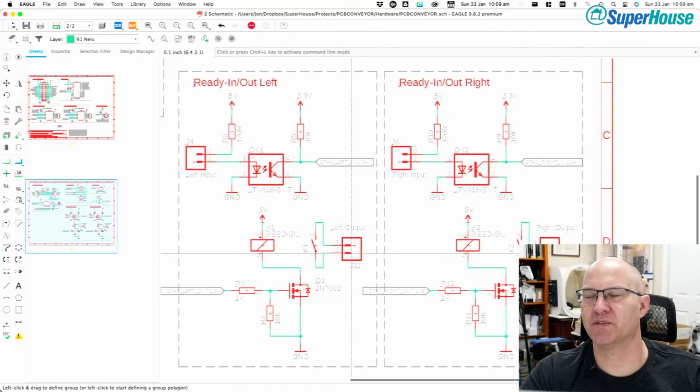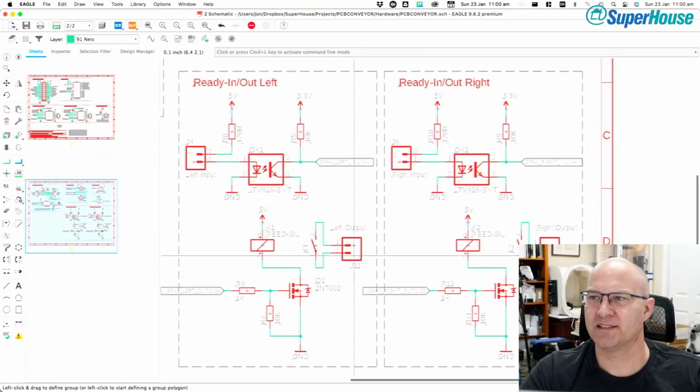The PLC or whatever it is in the next machine can simply put, say, 24 volts onto this, and then it'll take an input with a pull down on the other side or whatever it does. So with this, we can just switch this relay using this transistor to control this dry contact output. That's how we can send our status to the next machine.